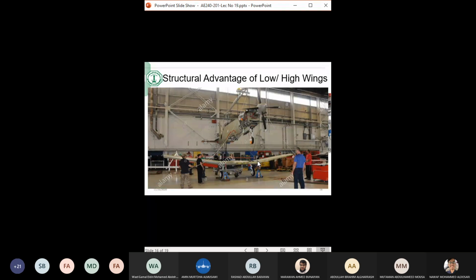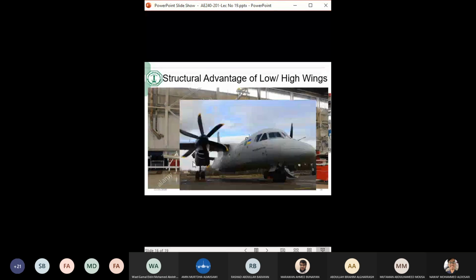Okay. This is good for low wing, and it's the same case for high wing. So for the transport aircraft that's produced jointly between the kingdom here and Ukraine, you have a high wing configuration where you have the structural wing continuous, no issues. You have room for the engine, and the landing gear that was very long, if I connected it to the fuselage, now I connect it to the engine pod and it retracts in the engine pod because it's not that long anymore.